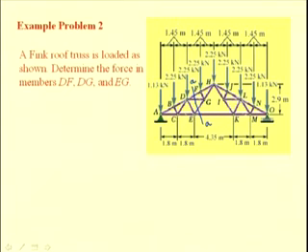So, now we have to see how we can determine one of the unknowns. Say the force in this member EK has to be determined. In order to determine this, we can consider another section, say BB, which passes through HJ, this member and this member EK.